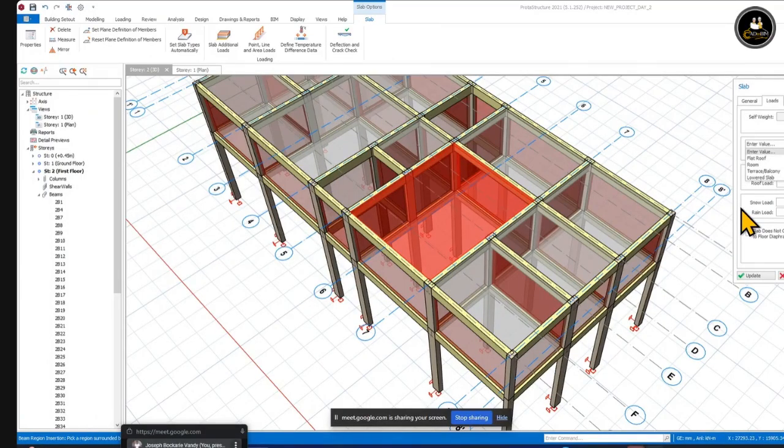So just choose, that's a roof, flat roof. Yes. So you can just leave it there. Even those slabs are now representing the iron sheets, the timbers, and everything, because that's only what you are interested in, their weight.